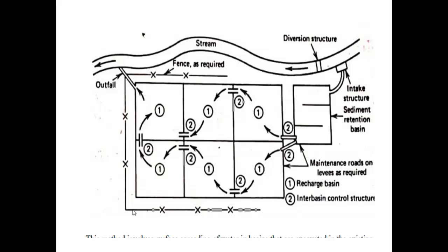In alluvial plains, the water may be diverted into one or more basins constructed parallel to the stream or the stream channel. The basins are constructed in pair or in series, the upper one serving as a settling basin for removal of silt. For effective artificial recharge, highly permeable soils are required, and maintenance of the water layer above the soil is very much necessary in the basin method.